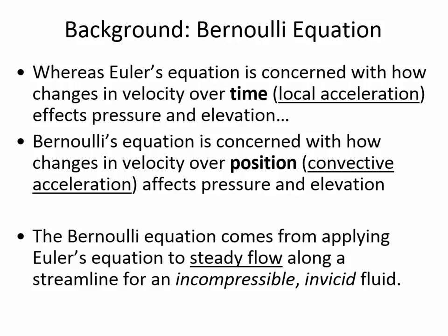Okay, so back to the idea of incompressible fluids. If you use Bernoulli's equation for gases, which are compressible, then you can expect some error from that. What Bernoulli's equation predicts may not be exactly what you measure in the lab or in the field, because of that deviation from the required assumptions behind Bernoulli's equation. So we've done 3 so far. Steady flow along a streamline for an incompressible fluid. And this last restriction is that the fluid we use should be inviscid. Now, most people don't know what inviscid means. It means a fluid with no viscosity.